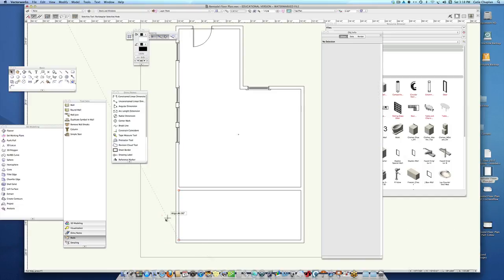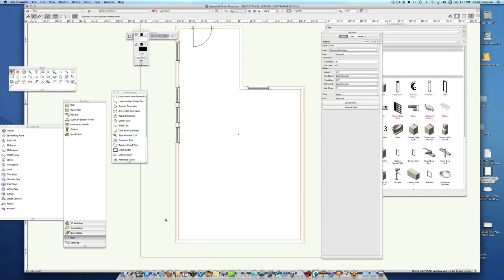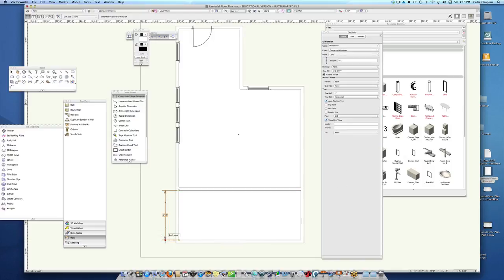And use our dimension tool. Oops. Let me do that again. Pick up some smart points. Oh, I see I'm in the first mode there. 1 point there, 1 point there, and I have 8'3". If I double click and I'll pin this corner, I can change that value to 10 feet and move the wall.